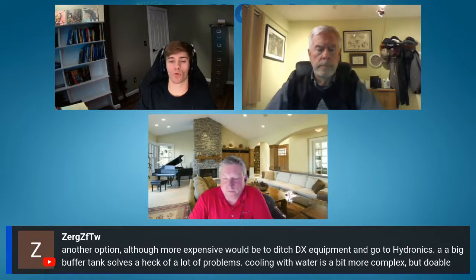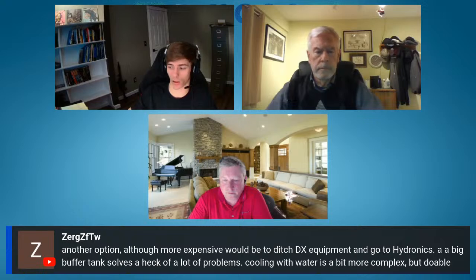If air sourced equipment is currently there, I'm sure there's probably some very oddball scenario where it makes sense, but I can't think of a reason to go to hydronics if it currently has air sourced. I can think of several reasons to go from hydronics to air sourced, but no reasons to go from air sourced to hydronics. Anyone else have any thoughts on this? Throw in some input.